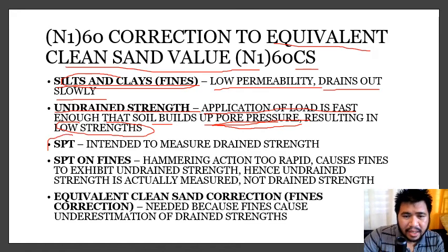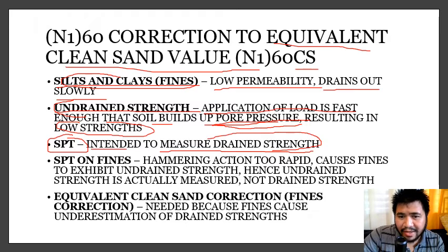Now, the problem here is that SPT is actually intended to measure drained strength, not undrained strength. And drained strength is generally bigger than undrained strength.